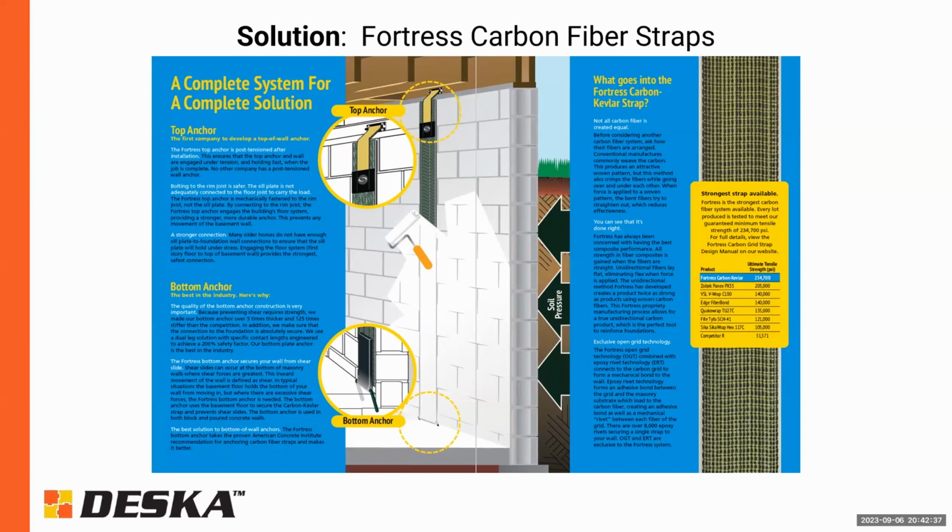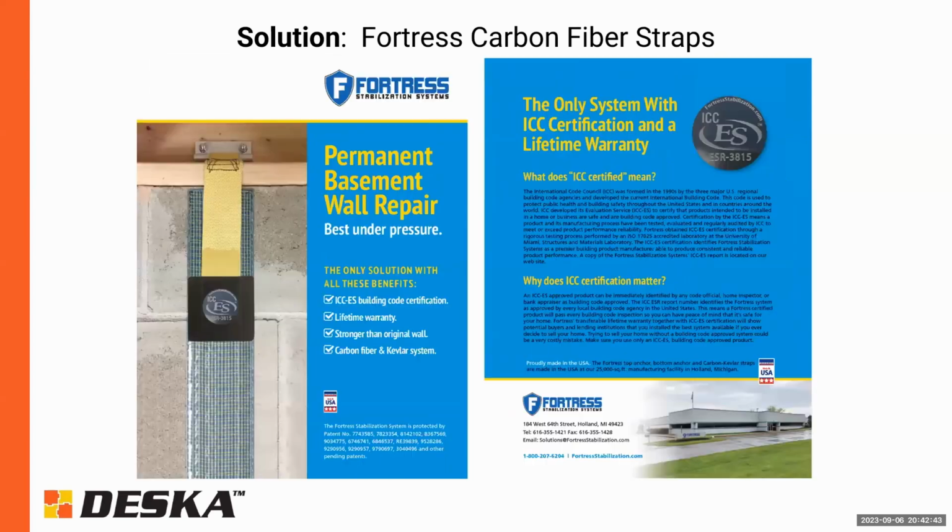And these straps essentially get epoxied to the wall and they get anchored at the bottom and the top. These particular straps are ICC certified. At least in the municipalities that we work within, they all require an ICC certification for any structural repair, and these are typically the ones that we'll use.